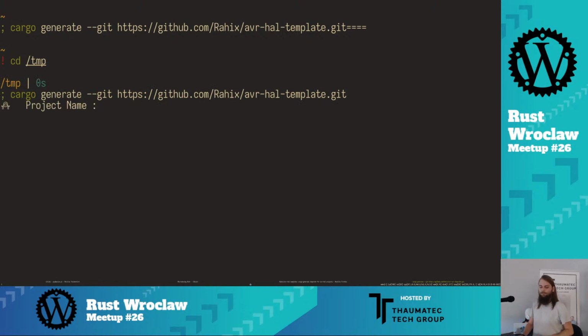Generate. And one thing before we continue, because I've been talking about AVRs as freestanding devices. It is possible to flash them when they are freestanding like that. I usually do it, well, not usually, but for the purposes of this presentation, I'm going to use Arduino. Arduino, if you don't know, is like a wrapper for this AVR, because I have this AVR inside, so this is pluggable. Let me show it also here. And then what Arduino provides is a USB port, so that I can easily connect it, and also provides this pinout, so it's easier to attach cables to it.